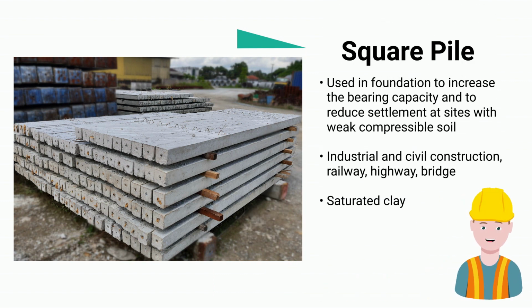Square pile. Square pile is used in foundations to increase the bearing capacity and to reduce settlement at sites with weak compressible soil. It can be used in industrial and civil construction, railway, highway, bridge. The most suitable type of soil is saturated clay.